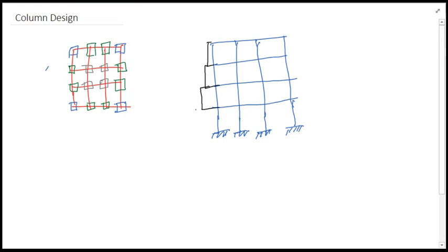This will be a typical axial force diagram, and all this will be negative value for the column. Axial force will be negative in the case of a column, just because it acts in the gravity direction, as you know. So from axial force, all these diagrams will be similar for all these columns. From story to story, as we go below, at the very lowest portion of the column, we will get the maximum axial force.